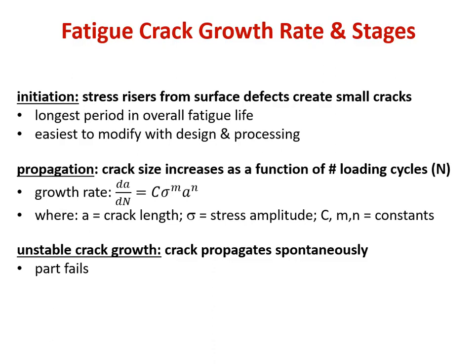It's easier to stop there, and there's much more available in the way of surface modification and design changes that allow us to preclude their initiation to begin with, which has the added benefit that we don't have to work so hard at inspecting and monitoring them. It's a very low cost, low risk, preventative approach to designing around fatigue.